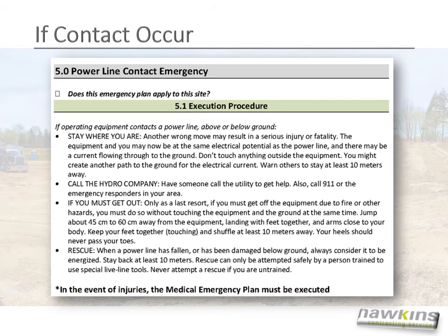Remember your emergency plan for hydro strikes. If you strike hydro, stay where you are. Another wrong move may result in a serious injury or fatality. The equipment and you may now be at the same electrical potential as the power source, and there may be a current flowing through the ground.